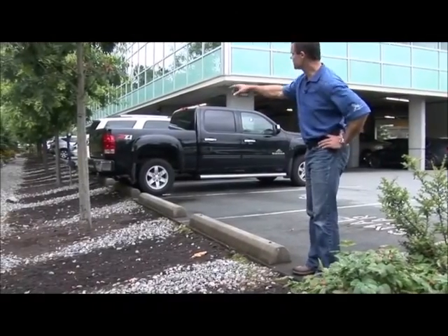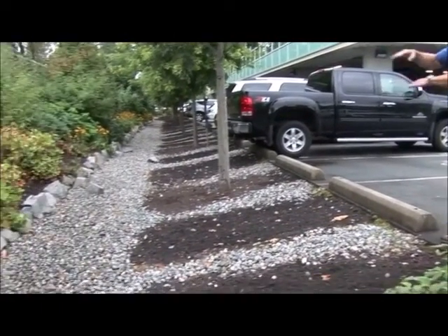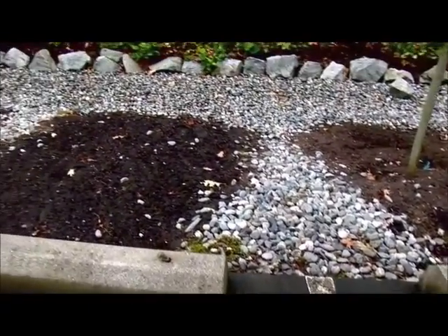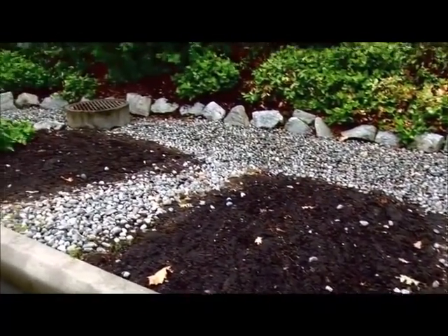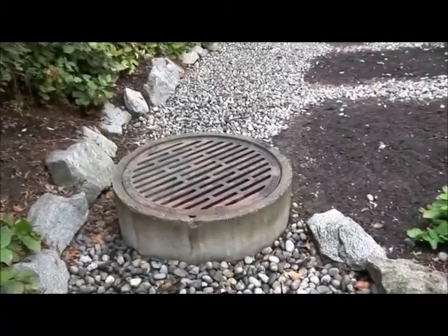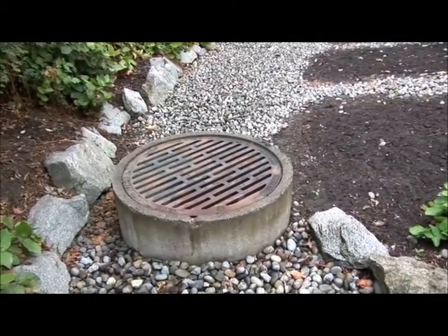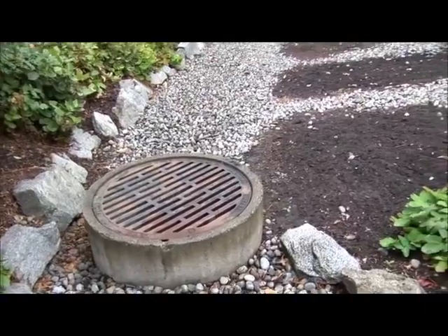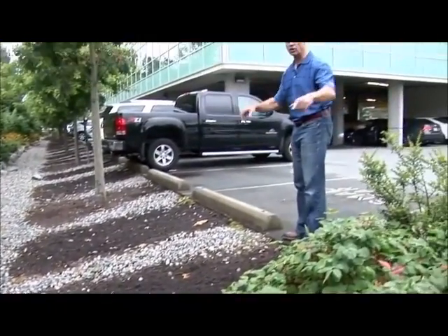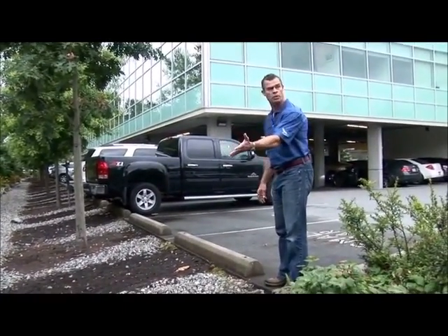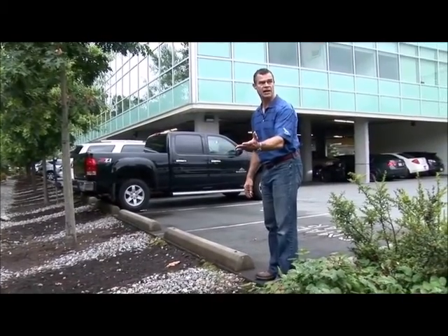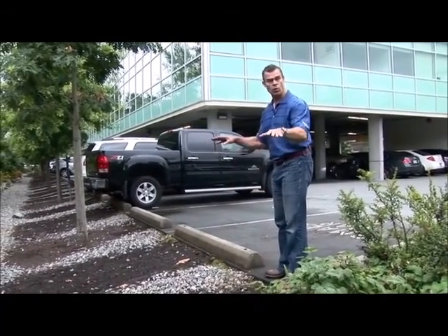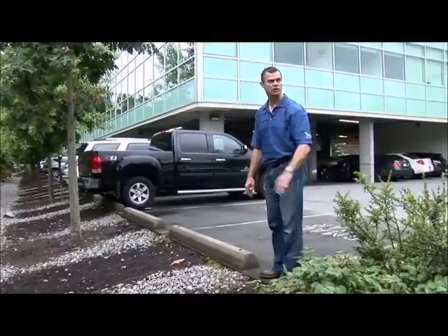This is an example of an unvegetated swale that collects parking lot runoff. The gaps between the curb stops allow rainwater to run off into the swale. During really, really heavy rain, this ditch will actually fill up and allow water to pond in it to a certain degree, and then the manhole has an open grate. So we're protecting against flooding by, when the water comes up to the lip of the manhole, it'll just exit out through the storm system.